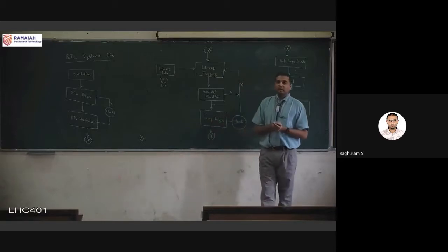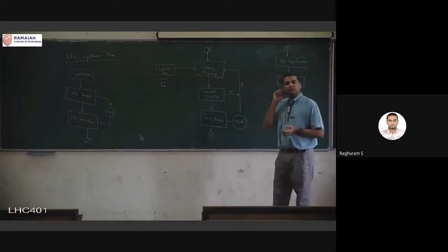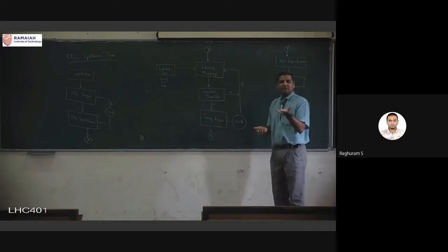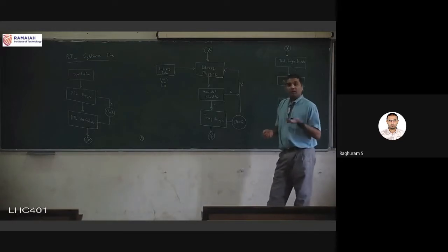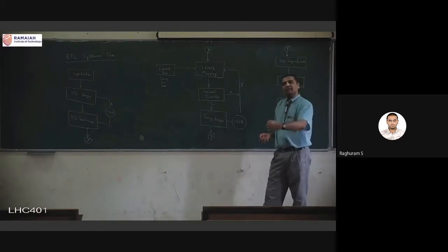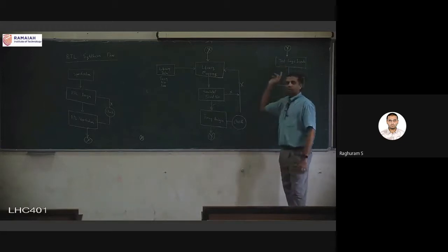But in post silicon verification, one very important thing is, are some particular gates, or some part of the circuit, having some fabrication error? We want to correct that also, because now I'm having the actual silicon implementation. Okay, how do I check that? I can give some input. I know what output to expect because I know the gate functionality. But I should be able to give that input, and I do that through the test logic.